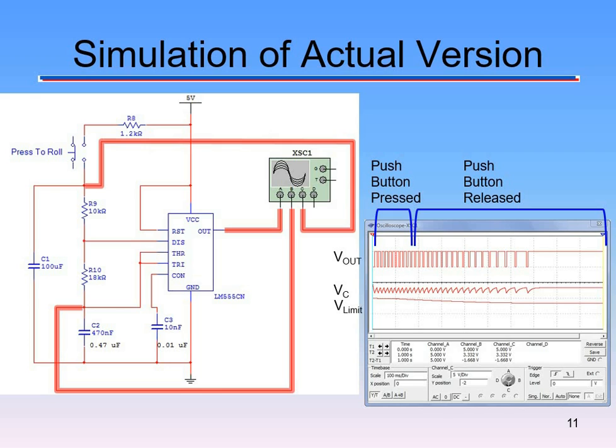Then when we let go, where it says push button released, this is where the other capacitor and resistor make a difference. Okay, why and how is the big question. Well, remember that time constant I talked about in signal analysis, tau, is RC? So resistor times capacitor. By adding that other RC in there, we change the time it takes for that capacitor to dissipate, which feeds the other capacitor. So we are able to notice how the signal changes.